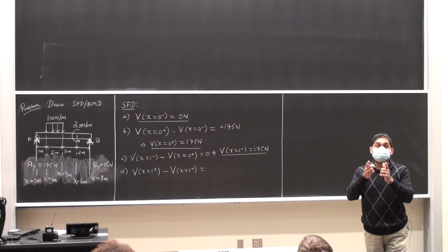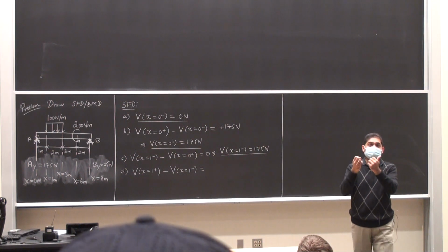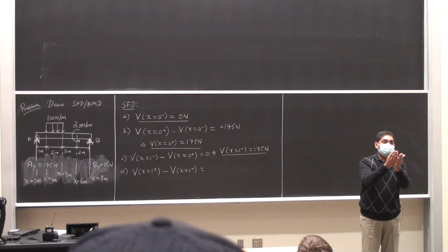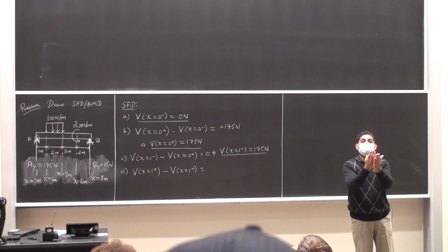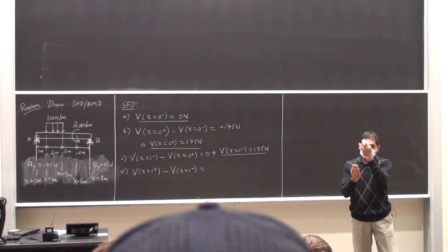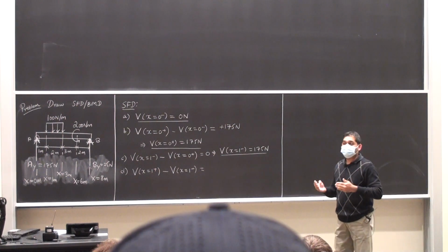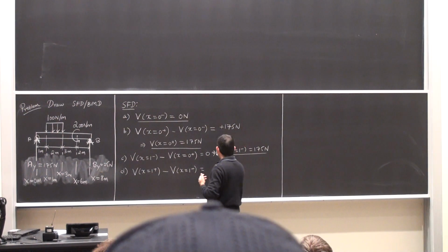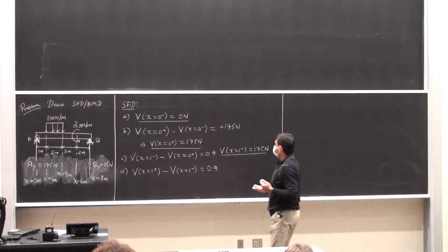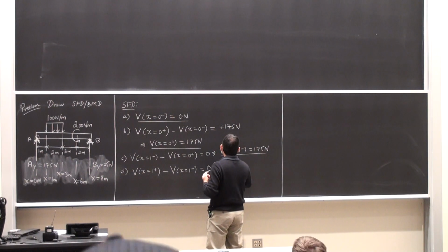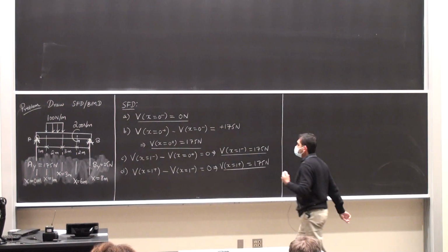Okay, great. So, if I have to take a distributed load and convert it into a single force, what's that going to be? It's going to be the distributed load intensity times the area under the loading curve. What's the area between 1 minus and 1 plus? 0. Which means that right at the beginning, I don't see the effect of the distributed load playing a role yet. Okay, so this is still 0. So there is continuity there. V at x equals 1 plus is still 175 newtons.